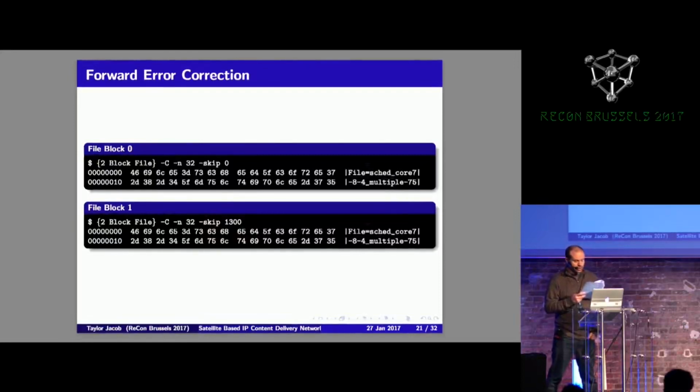I started examining other systems that used the same protocol. I noticed this ratio differed a little on different systems. C-band tended to use less redundancy than KU. This most likely is because C-band is less sensitive to interference and signal loss than KU band. So one of the more important observations that I happened to notice is a single packet transmission's FEC was an exact copy of the payload.